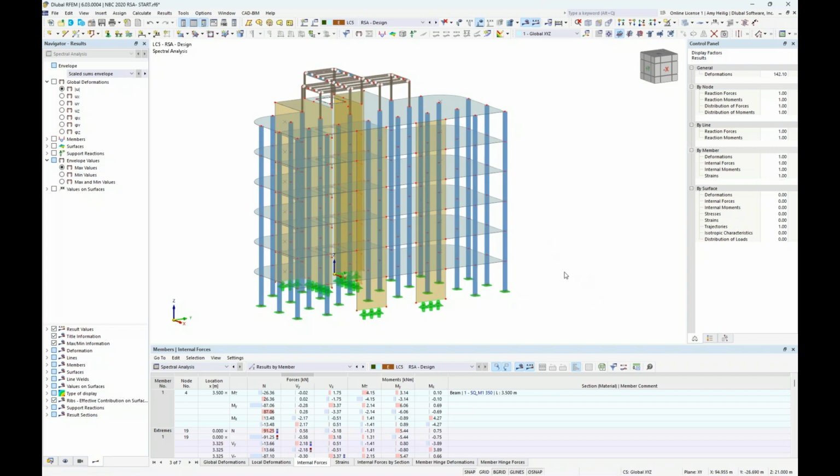Then we would move it over here to the side of the structure, change the member type to something called a result beam. And the result beam would then sum up all the internal forces here for all of the selected objects. But now in RFEM 6, we actually have introduced a new add-on called the building model add-on to better organize this result output with the response spectrum analysis.